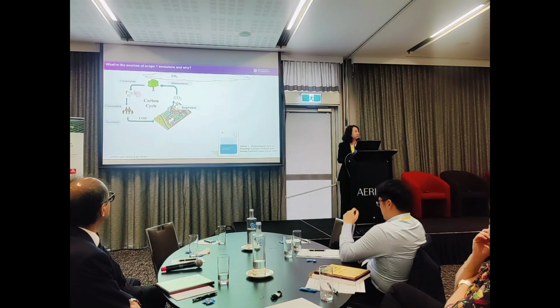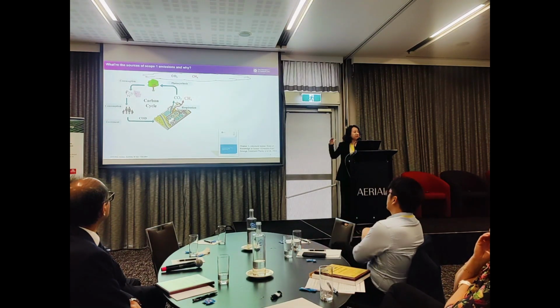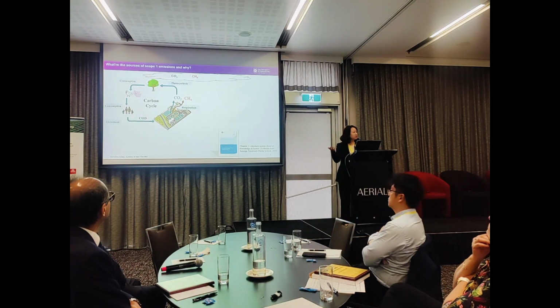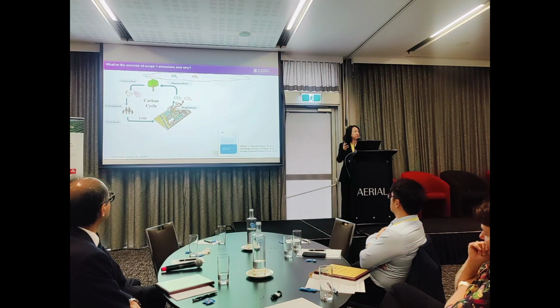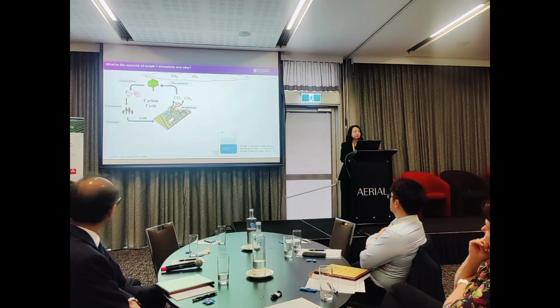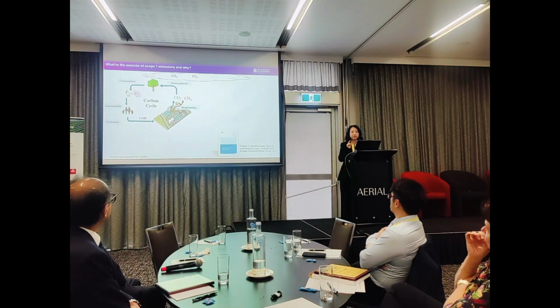However, we now try to generate biogas, or in some treatment processes there are a lot of anaerobic conditions. During sewer transportation and during anaerobic treatment, methane is being generated. Or when we try to promote more biogas generation through the CO2, we also generate methane. And if the methane is not captured but released, we interrupt this carbon cycle, and that becomes part of the Scope 1 emissions. So we have to be careful about this.